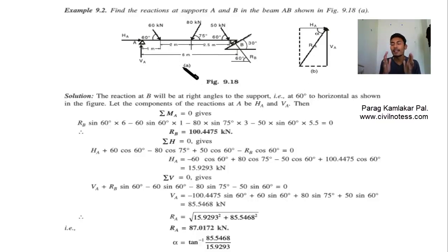Okay, one thing is important. Whatever angle it is, you have to take a name for that angle. I take the name as alpha. If that particular alpha is connected with the x-axis, then your x component is force times cos. If it is connected with the y component, like this side, then your component will be, I'm sorry, sine. So x axis always goes with cos, y axis always goes with the sine angle.